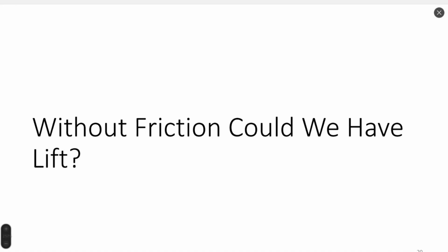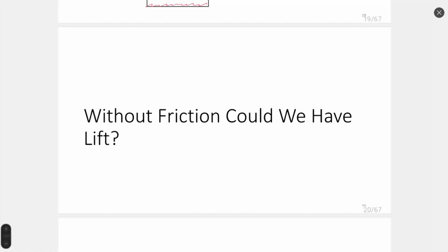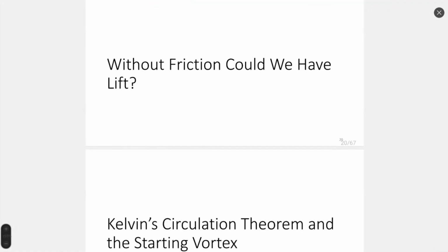Okay, at this moment, I would like to finish. Next time we could start from this question, or maybe better to start from the next question, because a simple answer, if we could have a lift without friction, is no. You can find in Anderson book why no, because real flow always is having friction, so lift is not possible, because generation of lift is a complex process of flow transformation, and real flow always is viscous.